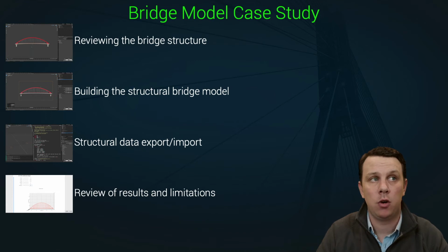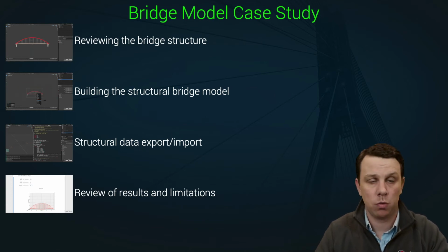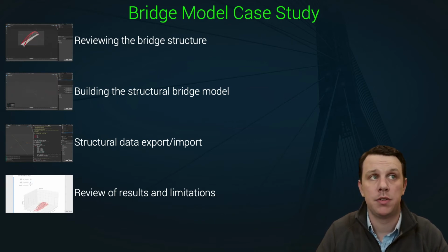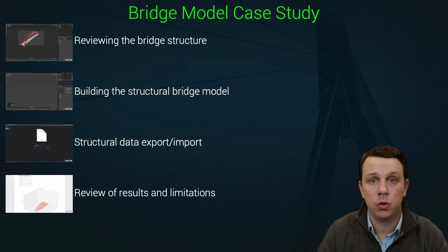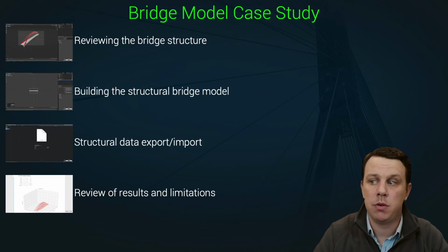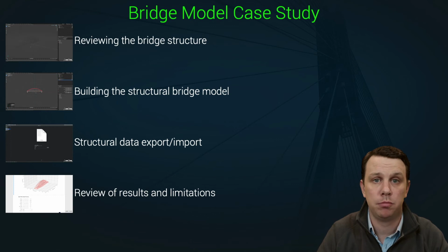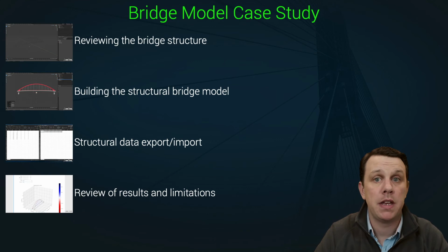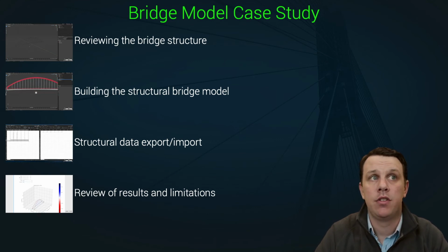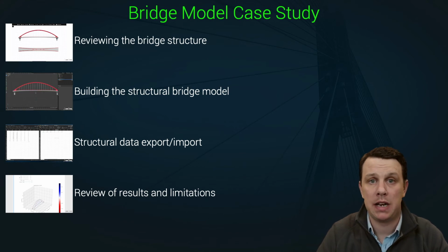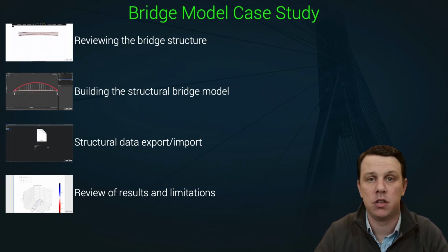Now, if you've only found Blender through this course or one of the other Degree Tutors courses, and so you're fairly new to Blender, you're going to find this lecture quite helpful because I'm going to be demonstrating some of the really powerful modeling tools that Blender offers us. So I'll be doing things like using modifiers, in particular mirror modifiers, which help us do non-destructive modeling, and these are a great way of speeding up your modeling workflow. I'll make use of reference images, and so if you're ever going to be modeling any kind of structure based on plans, you're going to want to make use of those plans as reference images in Blender, and I'll show you how to do that as well.